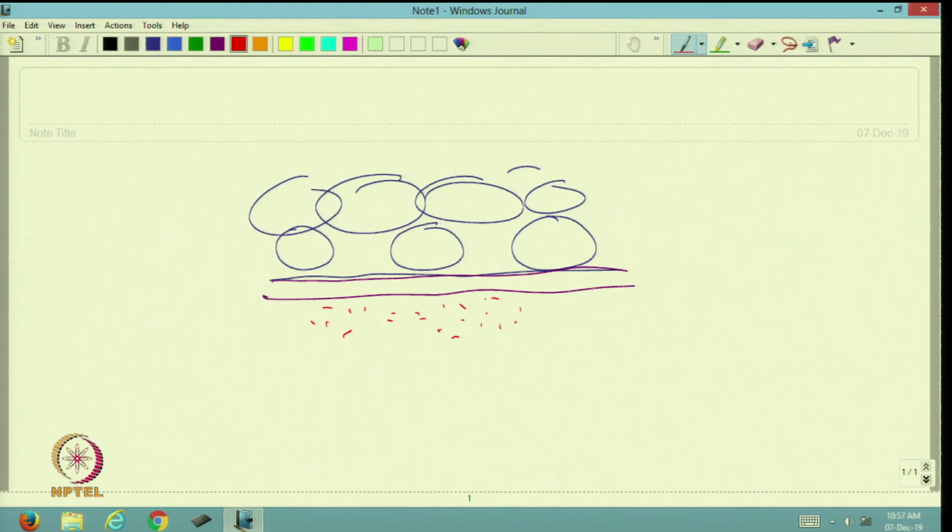The separation function is that the geotextile does not allow the soft soil to penetrate inside, but once pressure is applied, the soft soil will try to be pumped inside, and this type of situation will occur. So, this soil will try to penetrate inside. So, here the bursting situation is created.